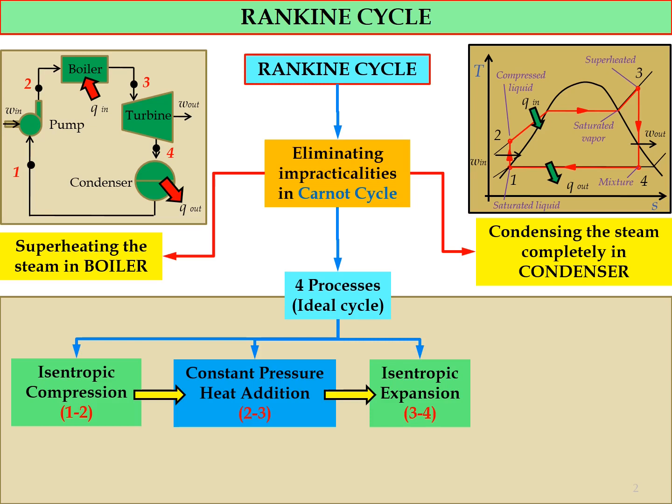So now at the turbine, we'll have W out, work produced, and during the process the temperature reduces, the pressure also will reduce, due to the expansion process. The energy from the superheated vapor is transferred to the rotor of the turbine. So at state number 4, the water condition is in the saturated mixture region.